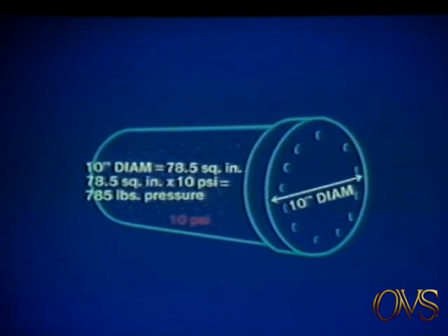If the flange is removed without bleeding off that last residual pressure, you might wind up with injuries from the sudden release of that force. Always remember that pressure is a hazard on any pipeline system, whether the line fill is nitrogen, water, or hydrocarbons.